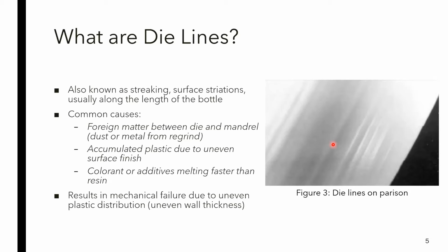With the slight differences in matching resins, colorants and additives, sometimes you'll have to create a different formulation and test it and make sure that everything melts at the same rate, so that something doesn't melt faster and burn, while your resin isn't even fully finished melting yet. Everything has to be basically a fluid before it gets pushed out.